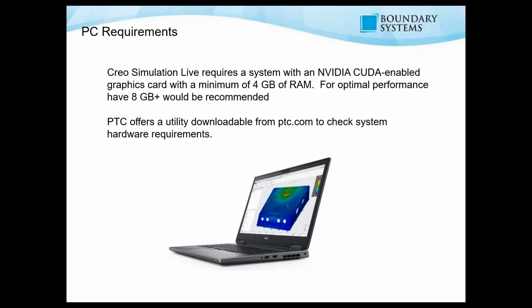Just some PC requirements that are really important for this product. You need an NVIDIA CUDA enabled graphics card. I'm using a 4 gig RAM card on my machine currently. They recommend an 8 gig card for optimal performance. There's also a utility you can download when you go to ptc.com.